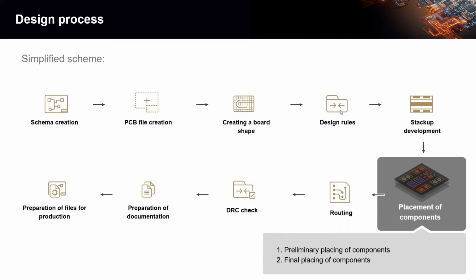Set up some design rules for component placement and routing, and preliminary design rules are created before you even place any footprints on the board. And that's what we're going to focus on today, of course. Then we create the board stack up. Hopefully that stack up is already created for you in a template PCB project. You would have a template PCB that's got a default layer stack up with about how many layers you think you need.